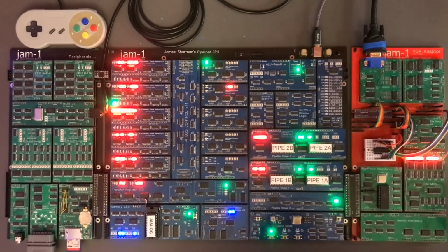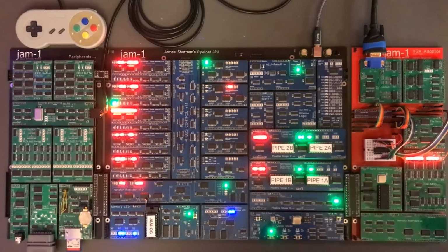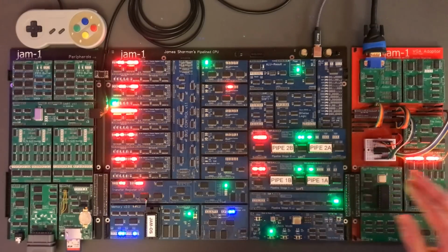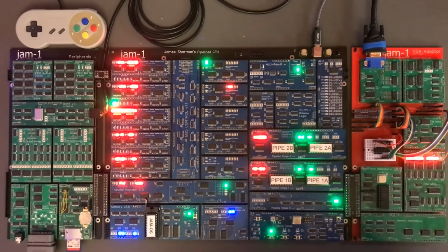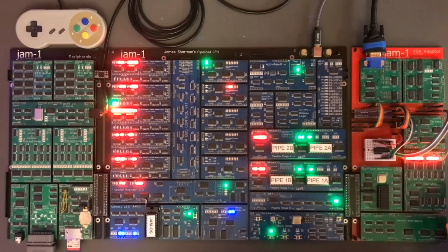I've got a couple of reasons for doing that. When I made the palette, I used a banking register to allow me to address a lot more memory than I've put into the map space, and I can do a similar thing on the sprite data. I want to use the same memory chips for every piece of memory in the VGA circuit, and those are 8 kilobytes, and so I don't want to use just half of it in 4K. But if I bank it into a 1K slot, I can make use of the entire memory chip and give a little bit of general purpose RAM back to the system.